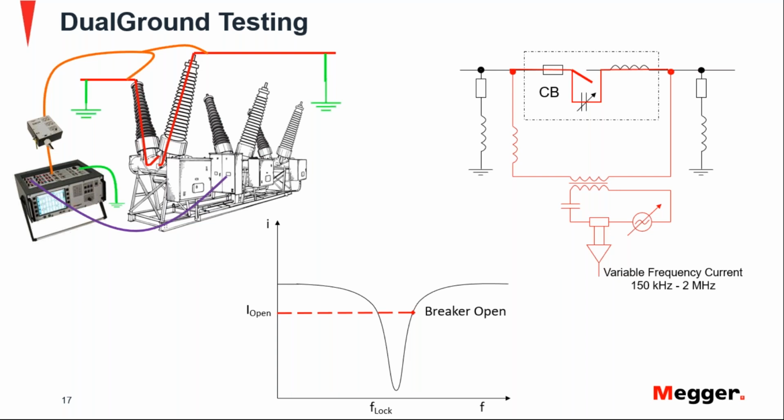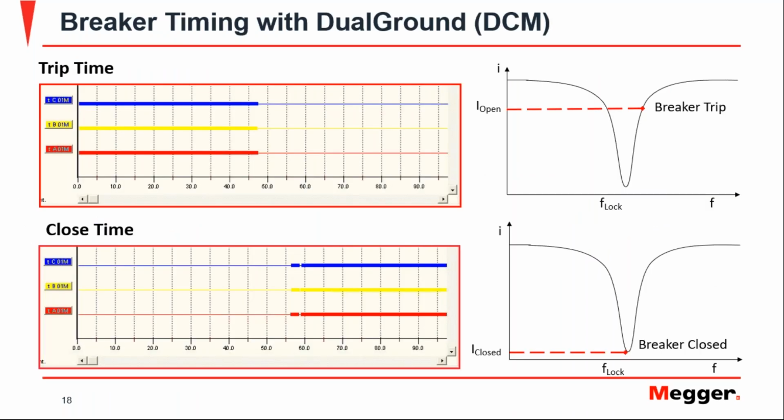But you're going to increase the safety and you're going to increase the speed and efficiency during tests, because now you don't need an authorized person to remove these. And when I say authorized person, it's because sometimes it has to be a very specific crew, and sometimes they have to talk to control to be able to disconnect, to do any procedure. So that represents time. If you don't have to do that, you just go there, ground, connect your leads, and you don't have to talk to anybody else until you finish your testing. So that increases the speed of the test and of course the safety.